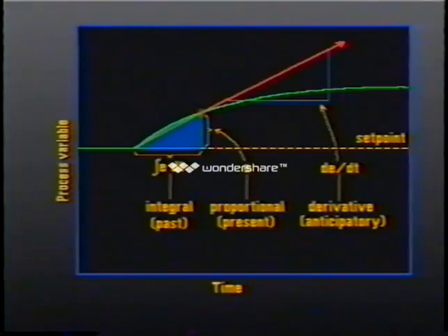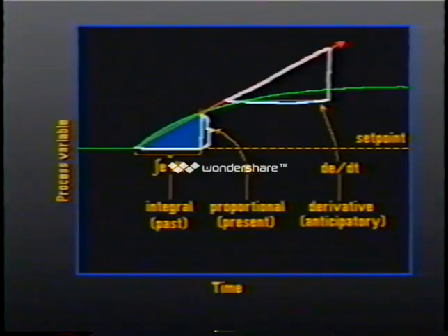There is a good reason for this. The P&ID control algorithms contain every element that is important in the feedback control of a process variable. The proportional mode deals with the process error as it occurs, or in other words, with the change itself. Integral action deals not only with the magnitude of the error, but also with its duration, and the derivative mode adds a final control dimension by considering the speed at which the change is happening.